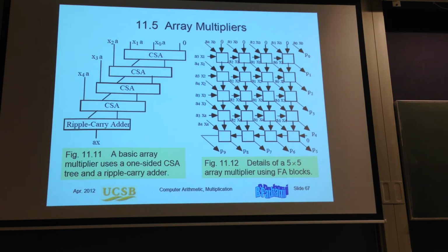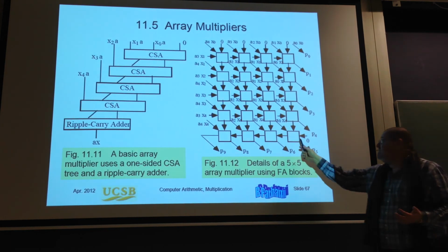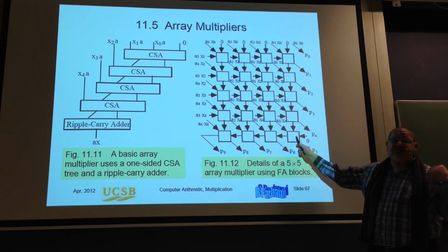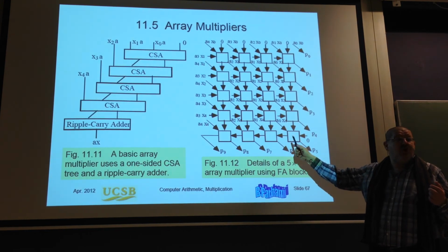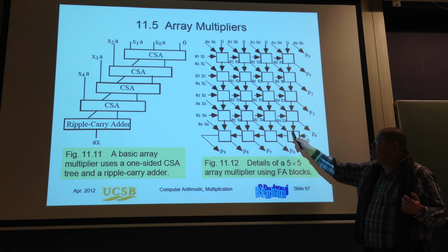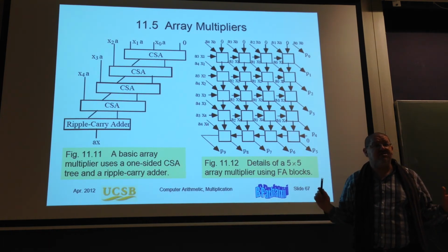Yes? You can make a kind of pipeline. Yeah, it's very good for pipelining. And next thing, it's very regular. These boxes are all the same. Those are full adders. There are local interconnects. There are no long distance interconnects. You see, I only connect with my neighbors.